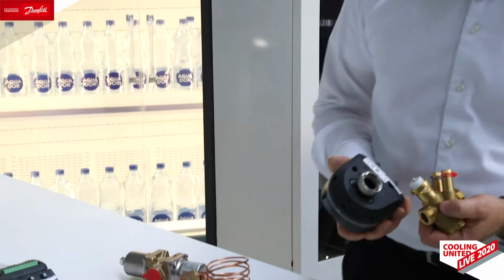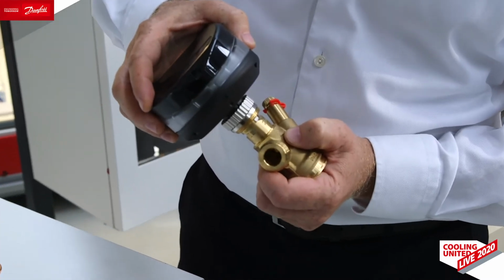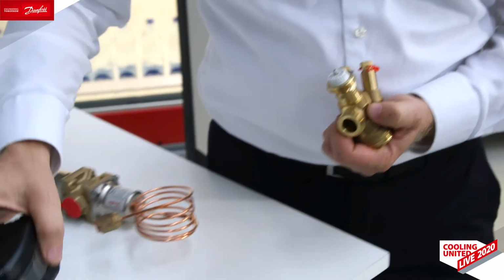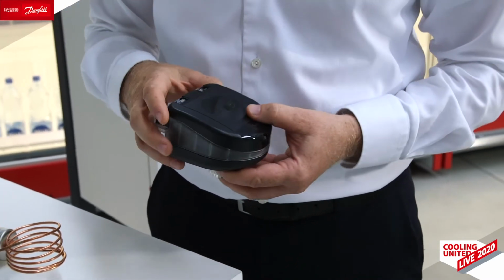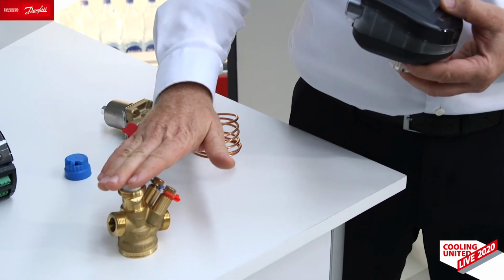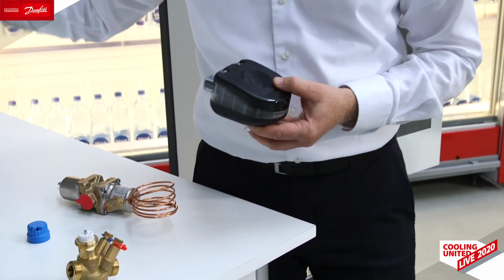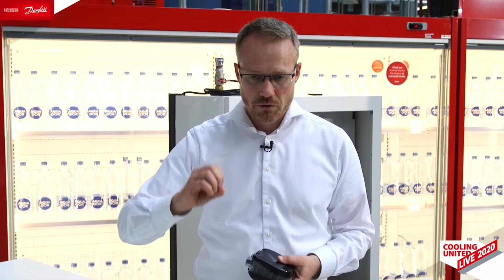Another thing that we can do with the ABQN valve is that we can put an actuator on. In this case, this is a Novacon actuator, and the Novacon actuator is actually quite smart. It has the ability to take a temperature input, also other types of inputs, and then control the flow rate based on that input. So if you're defrosting your case and your condensing unit is shut down, then you can shut off the flow. In other cases, you may see that the temperature is low, and you can also reduce the flow rate, thereby also providing additional energy savings, additional control features for your case.